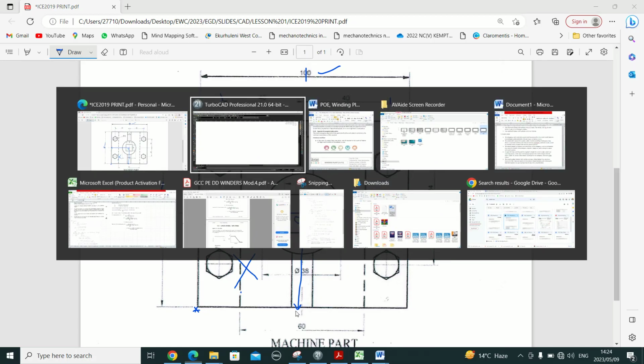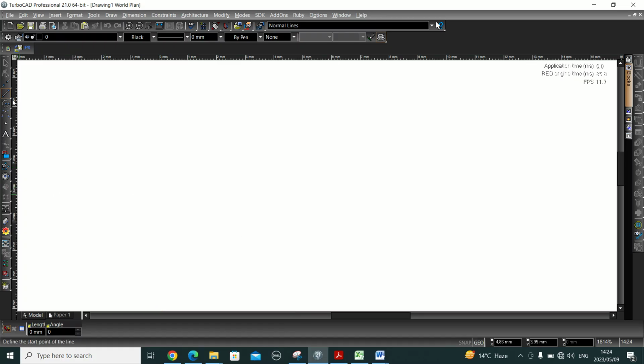So let us draw our rectangle. Go to the line tool, click and hold, a menu will pop out, select a square, change now the thickness to 0.5, press tab on your keyboard, you see now something is moving. We set our X to negative 50 and our Y to negative 44. After that, press enter on your keyboard.